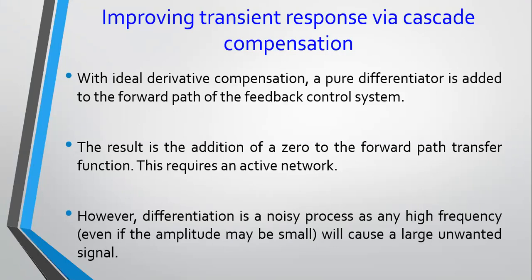In this case, we're going to use a differentiator. Remember, in the case of steady state error, we use an integrator. Now, in this case, when we're going to design the PD controller, which is going to be a pure differentiator, we're going to be dealing with the transient response.